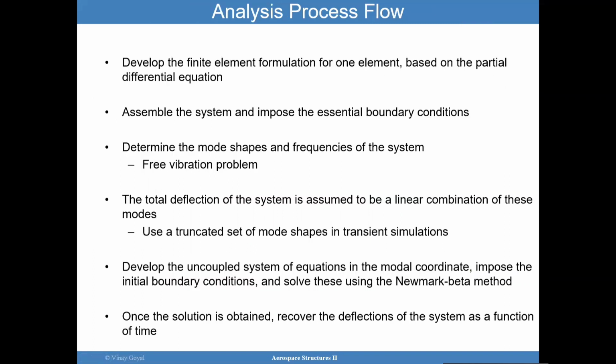So the analysis process flow is the following. You have a partial differential equation, you discretize the equation into a discrete number of elements, and you get a discrete number of degrees of freedom. And what you want to do is calculate the mode shapes and frequencies for that system. You're going to have a discrete number of them, not an infinite number of them, only because we discretized the continuous system. Get the free vibration problem. Try to understand the dynamic characteristics of the system, because that's going to be very important moving forward.